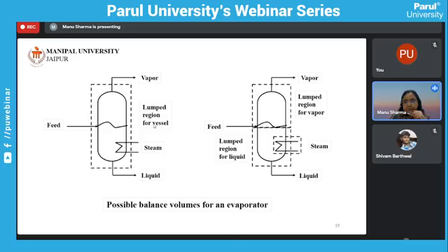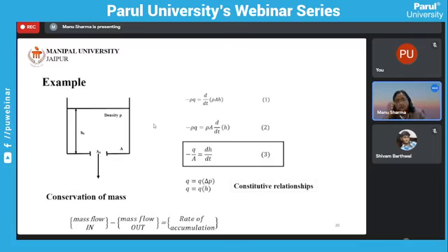However, if we have taken vapor phase as one system, liquid phase as another system, and the heating element as a third system, and we have developed individual mathematical expressions for that, then for individual regions we will be developing lumped parameter models. So depending on the type of process that we are dealing with, this is for the non-reacting system. If reaction is occurring, then obviously you have to go for the distributed parameter system, particularly if this process is non-isothermal.